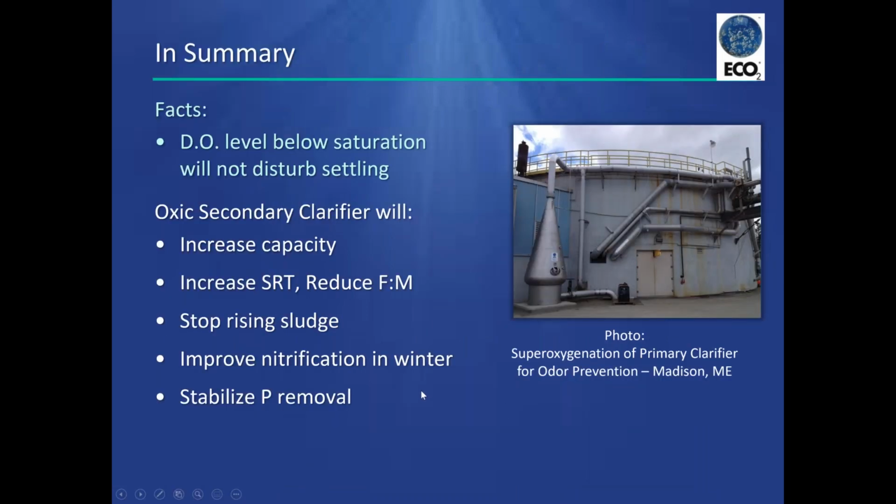In this slide, we would like to summarize. We raised the DO to a very high level compared to the 2 milligrams per liter normally associated with it, but we keep it below saturation so that it is kept in solution and not lost.